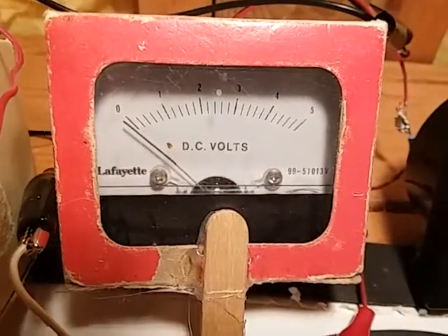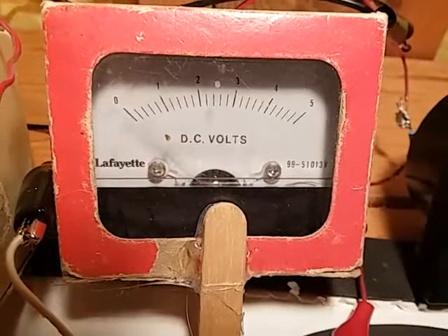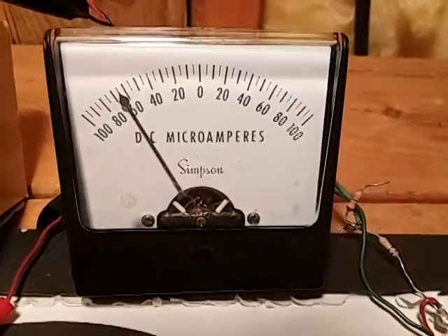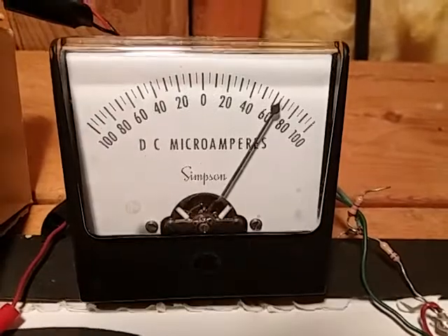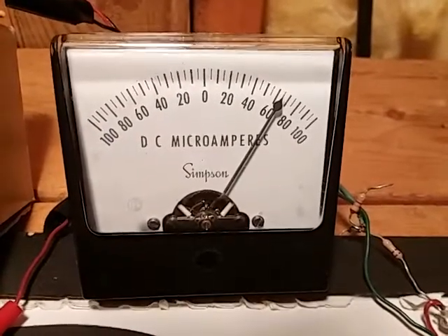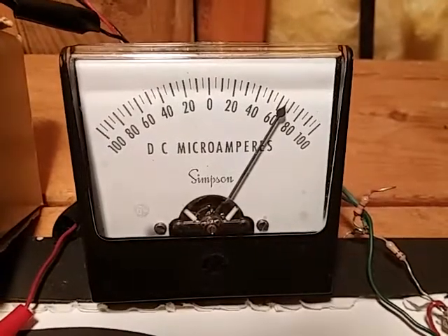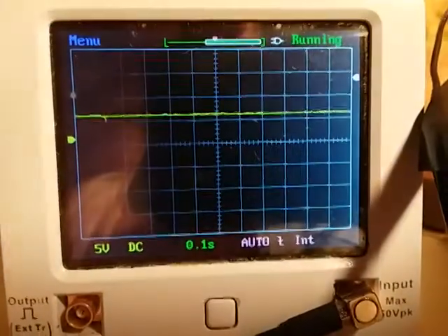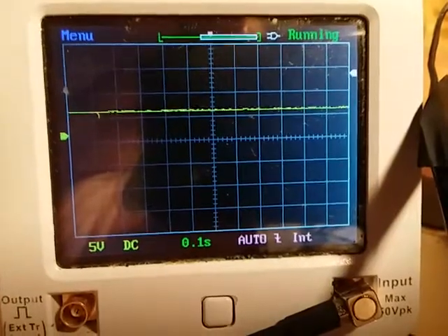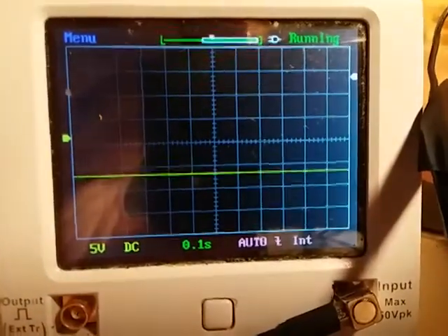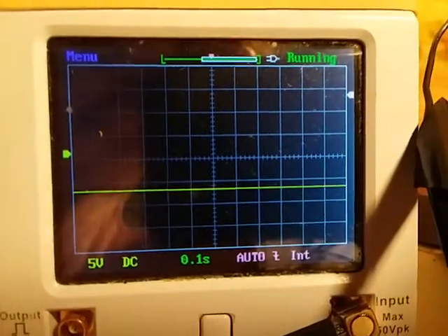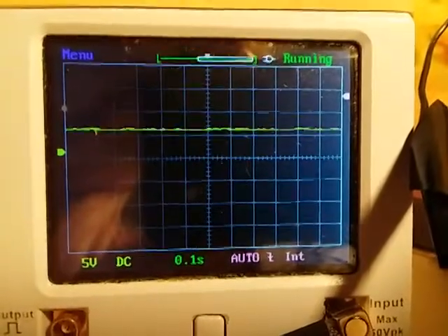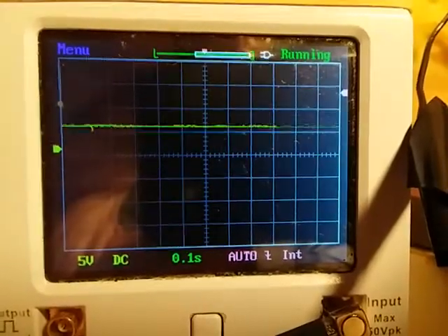Point is, control systems are very stable when you build them correctly. And lastly, the output. The output is at minus 6.5 volts or 6.5 diopters, going to plus 6.5 diopters. And of course, back to 6.5 diopters. Lastly is the error signal multiplied by 50. This shows two things. It goes into saturation because of the times 50, and oscillates at about 5 hertz. So that's characteristic behavior of a control system.